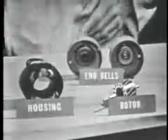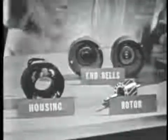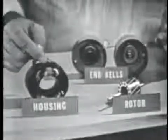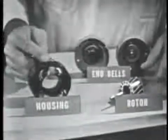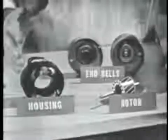Very good, Bob. Now to summarize, let's complete the TVI guide. Okay, I'll take item 1, which asks you to identify the major parts of the induction motor. A, the end bells. Remember, they just hold the bearings for the motor. B is the housing and the stator windings. Very simple and very rugged. And C, of course, is the rotor. Right. There are no slip rings or wire windings. And of course, overall construction is very simple, very rugged.